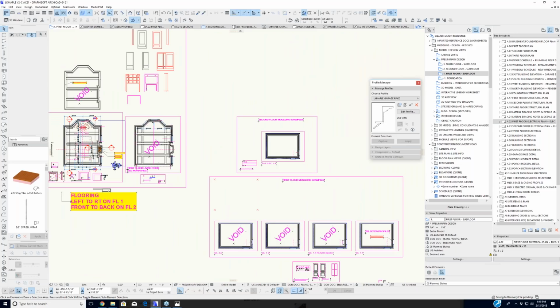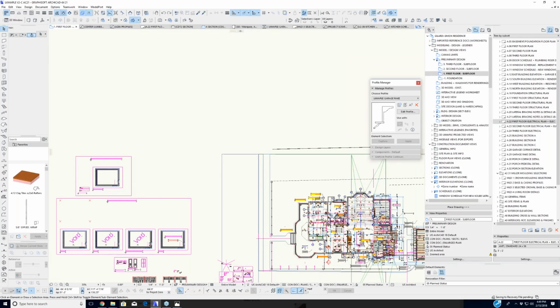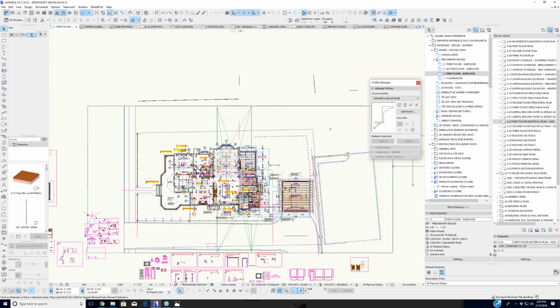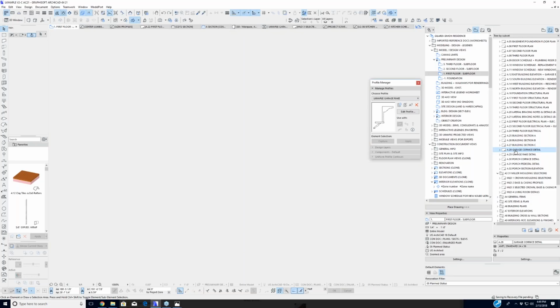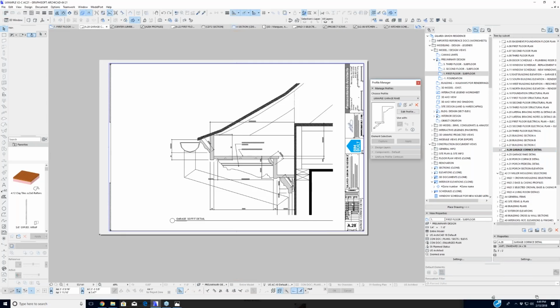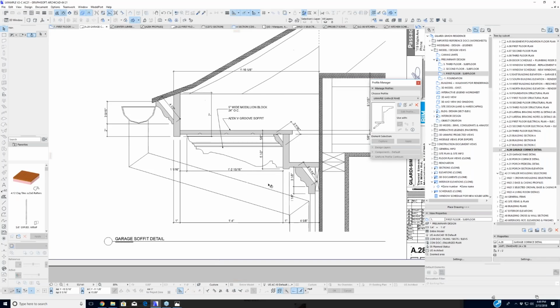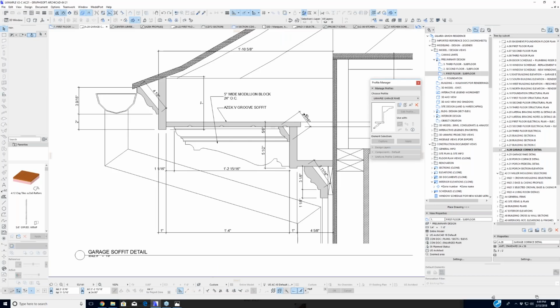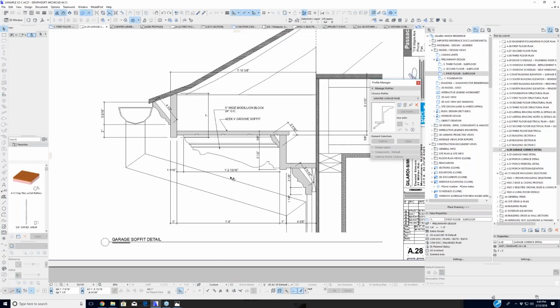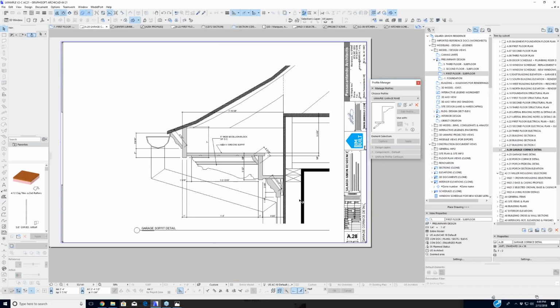But as far as details that went into a construction set of drawings that went out to the building permit, for all of the exterior rakes and cornices and brackets, that was on a detailed sheet, which then became a link to the drawing. Now this might have come afterwards. This is actually doing a one-to-one scaled drawing, which I would print out here and then hand to the builder, as well as add these dimensions. All right, so there we have certainly one-to-one detail, so high level of detail in there.